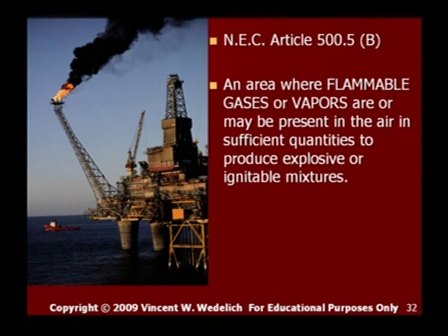NEC Article 500.5B: an area where flammable gases or vapors are or may be present in the air in sufficient quantities to produce explosive or ignitable mixtures. This would be a Class 1 location.